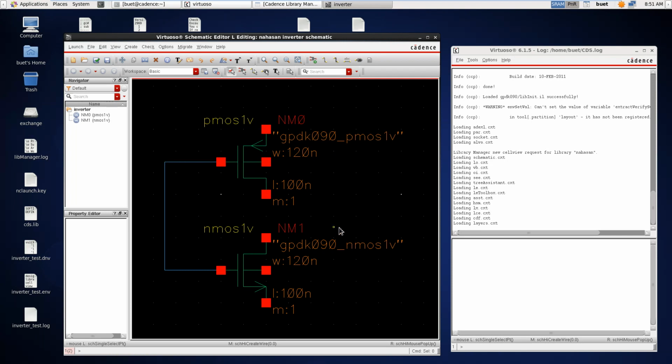So again you have to connect the two drains, the drain of PMOS and drain of NMOS. As you know, on the bottom side the PMOS drain is situated, and on the upper side the NMOS drain is situated. So this is source, this is gate, this is body, this is drain, this is again drain, this is gate, this is body of NMOS, and this is source of NMOS. So I will just open one picture.